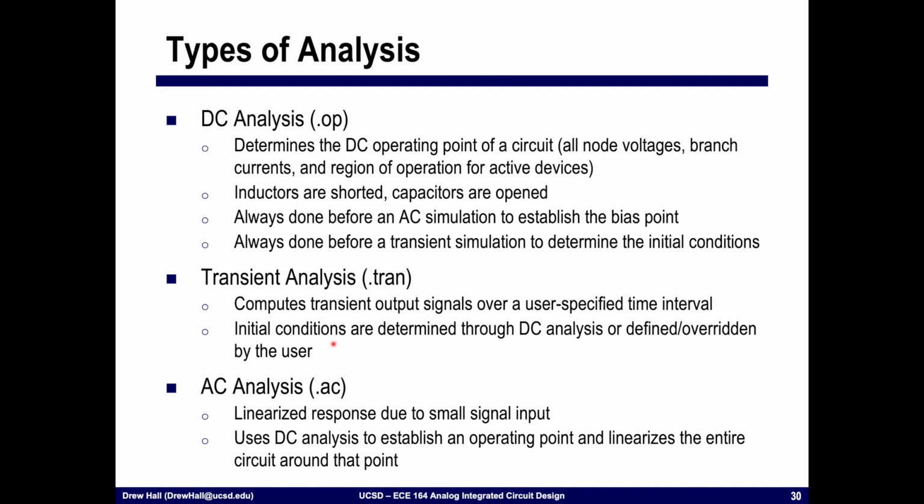And then lastly, we can use AC analysis, where we're going to look at the linearized response due to a small signal input. Okay? So there are other types of analysis that SPICE supports. These are the main 3 that we will use in this course, and these are probably the workhorse that you will use in general throughout your career.